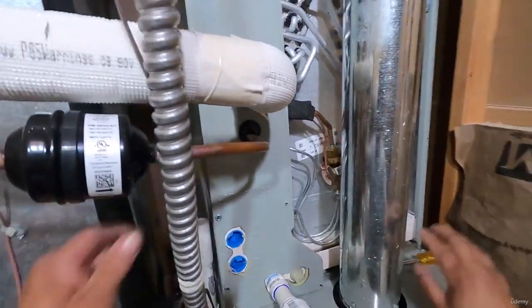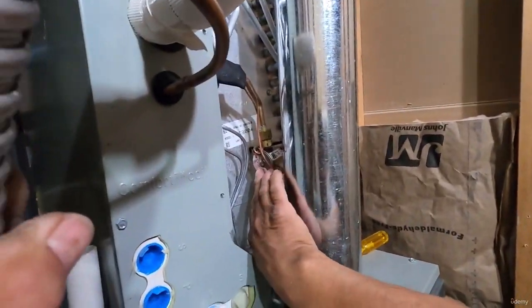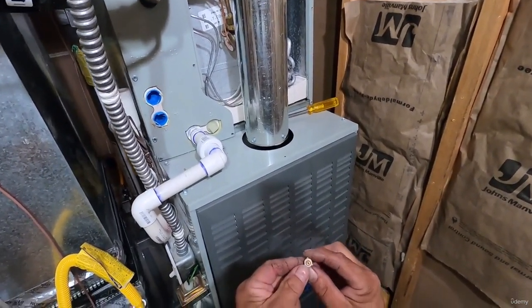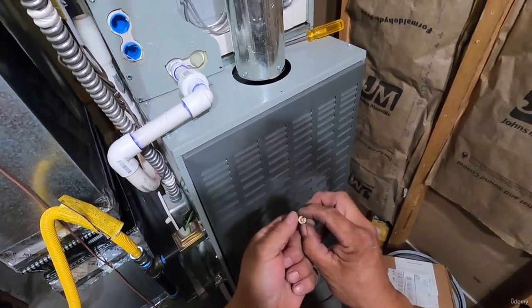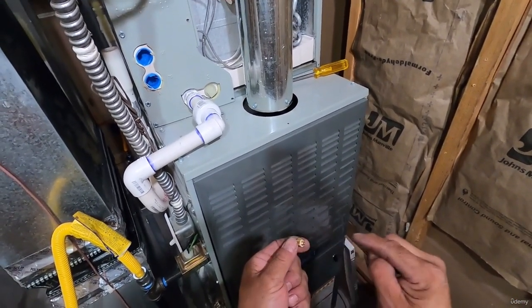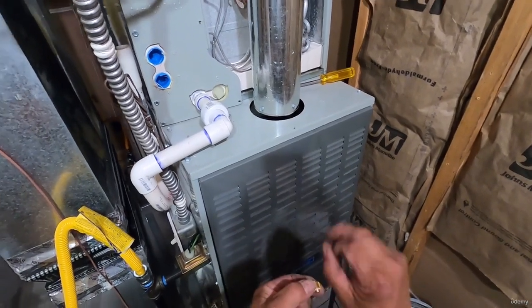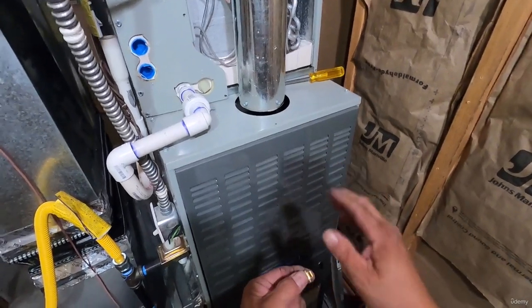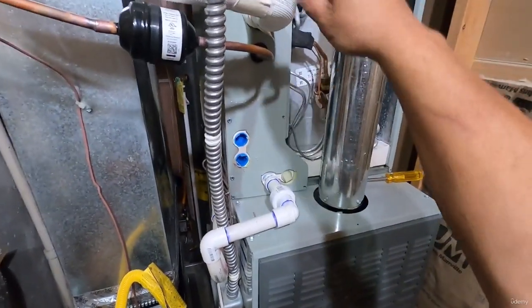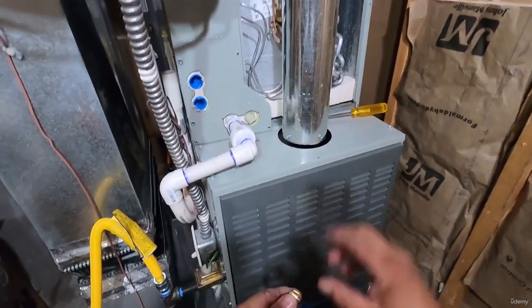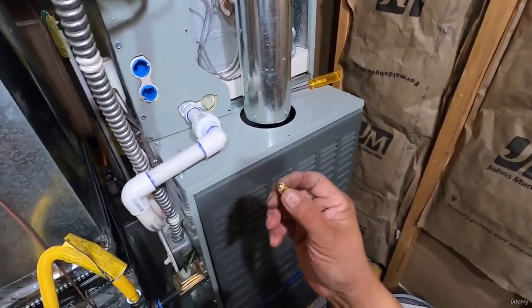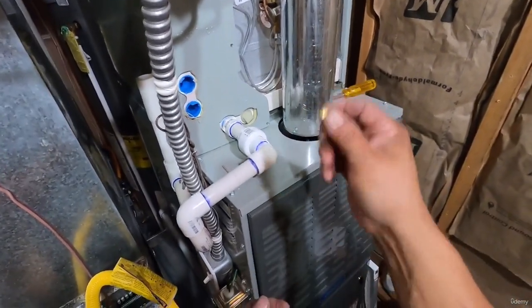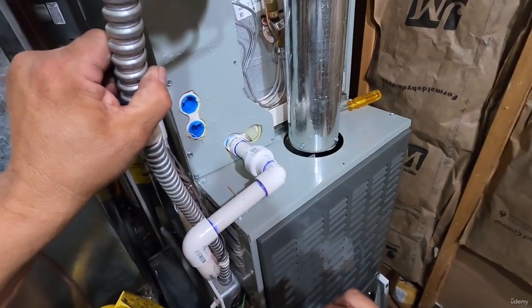So you'll either have an expansion valve, or you could have a piston. And you can see how small this orifice is, and that high pressure liquid will flow into there and come out the other side. It'll just spray it into a cold vapor, and you'll have a little bit of liquid, but by the time it gets through the coil, that liquid will be evaporated. It'll be just vapor. So you can either have a TXV or a piston, and these are the main components of an air conditioning system.